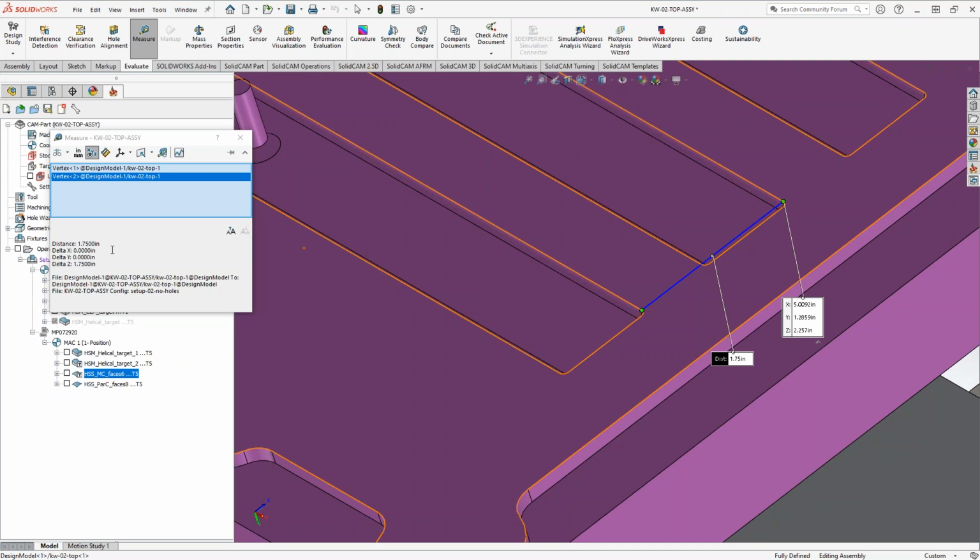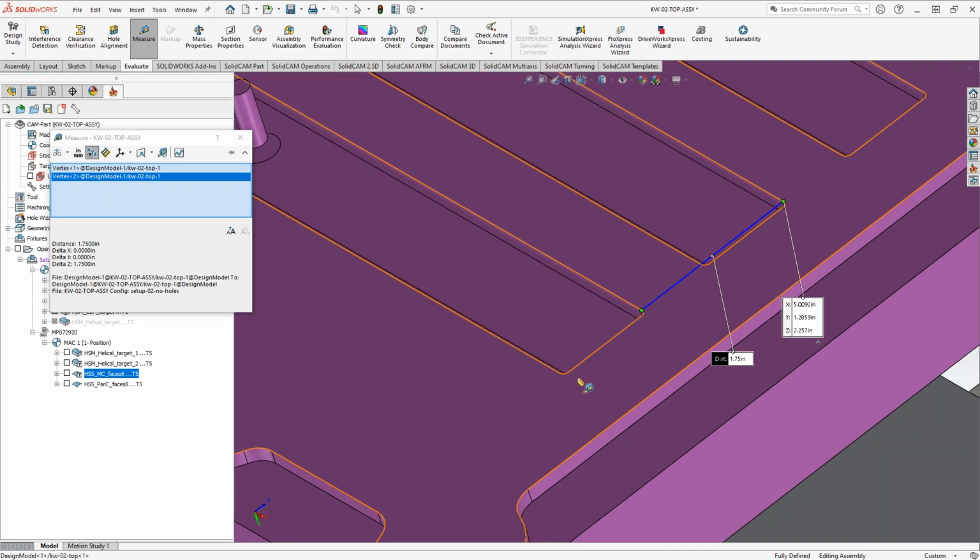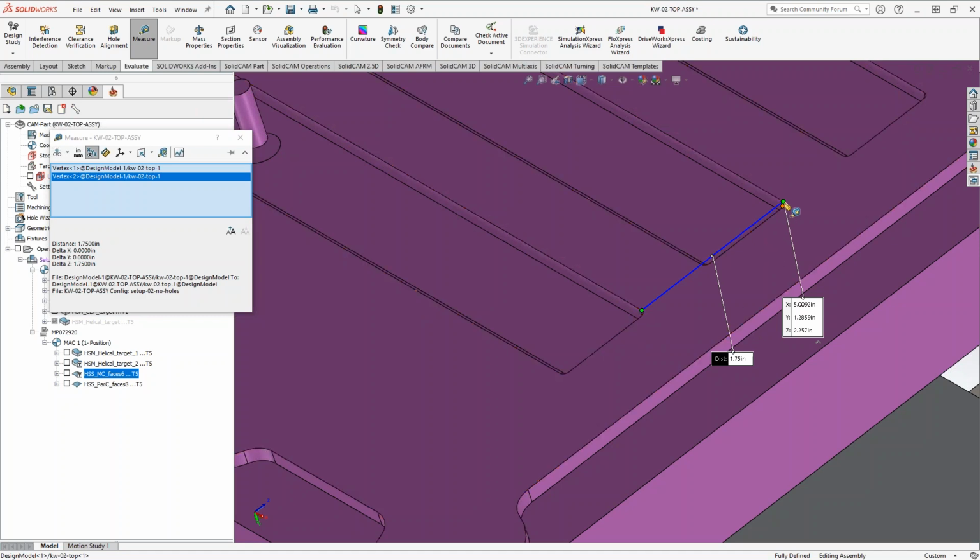Yeah, I agree. It does come up a lot because transform is literally translating or rotating from one instance to the next. So if you were to do just the gap, you're asking it to just travel across that distance there, and that's not what you need. When the toolpath starts from there, you want it to start from there as well. So that is a direct translation. So yeah, exactly there. That's where I got that 1.75. It's just from that corner to that likewise corner over there.